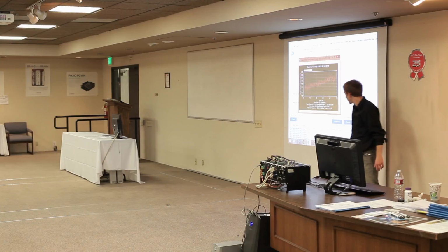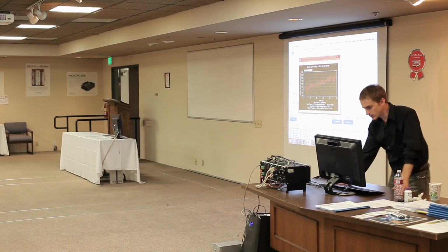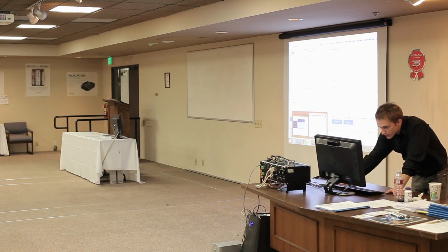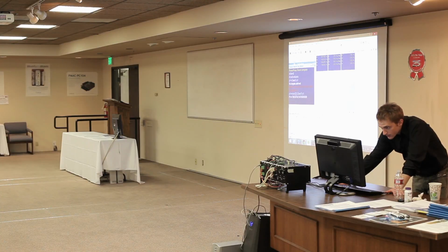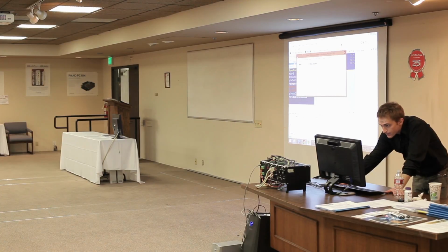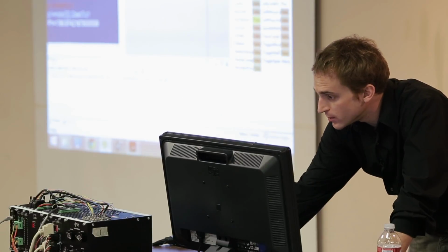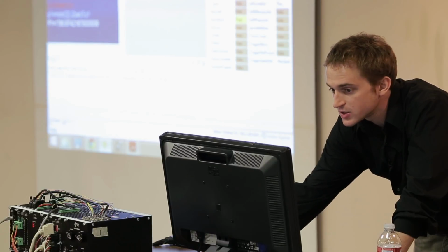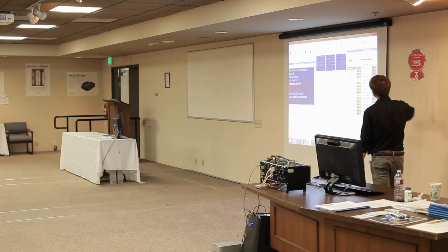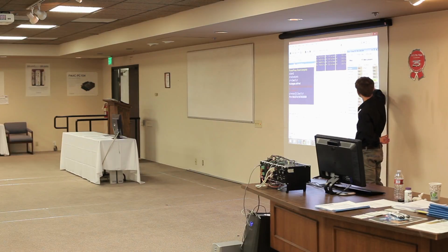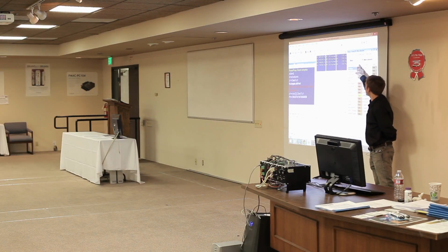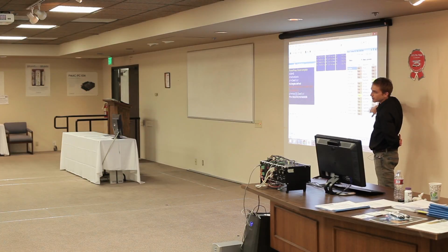So that looks bizarre. I'm going to check my motor status, make sure I don't have any faults. If you have a problem, I recommend keeping the motor status window open. You can get it by clicking on status right here in the toolbar, and then you can drag it to the right. And scrolling to my motor 3, I can look for any faults here. So if you're on a limit or something, like you have the limits on, you won't be able to do the current loop step and so forth.